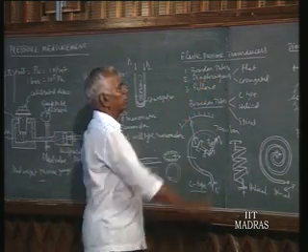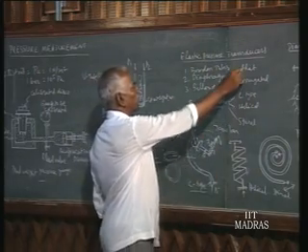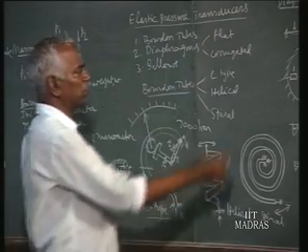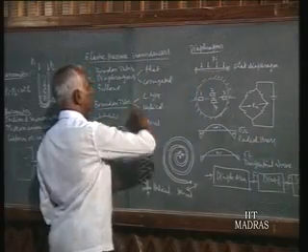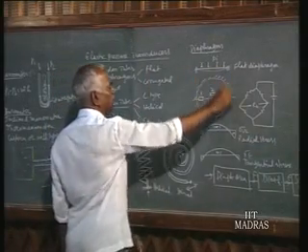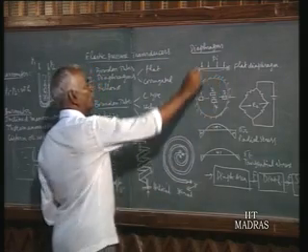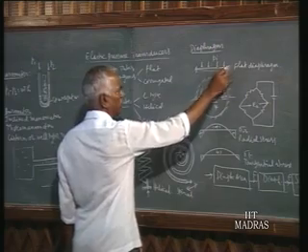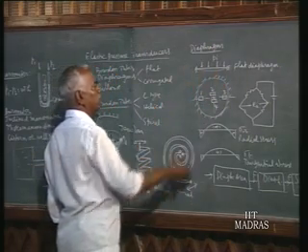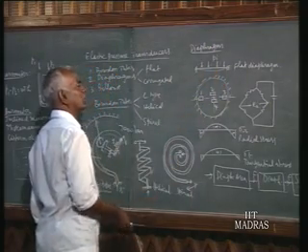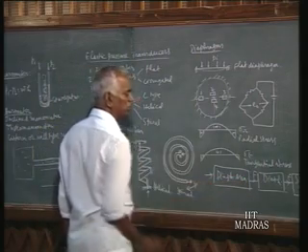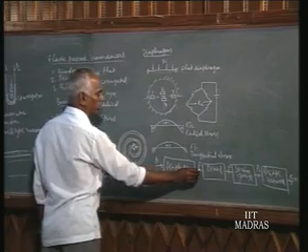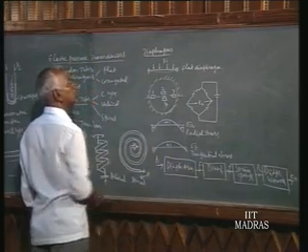So the next one is the diaphragm. We have two types: flat diaphragm and corrugated diaphragm. A flat diaphragm is just a thin sheet, again made of spring material, fixed at the rim. When you apply pressure on one side, you find it deforming like this, and that means the pressure is converted into force, according to this signal flow diagram. This is pressure, and when we apply it over an area, it converts into force: pressure times the area of the diaphragm.